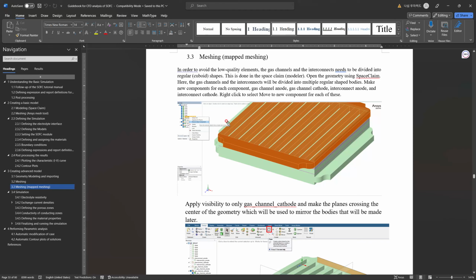and in the project window the first part is that we will duplicate it. So let's duplicate this geometry and mesh, and we will start from there. Okay, now for this mesh, because we need to make it a map mesh, we will clear the generated data in this component, and here we will make the map mesh.